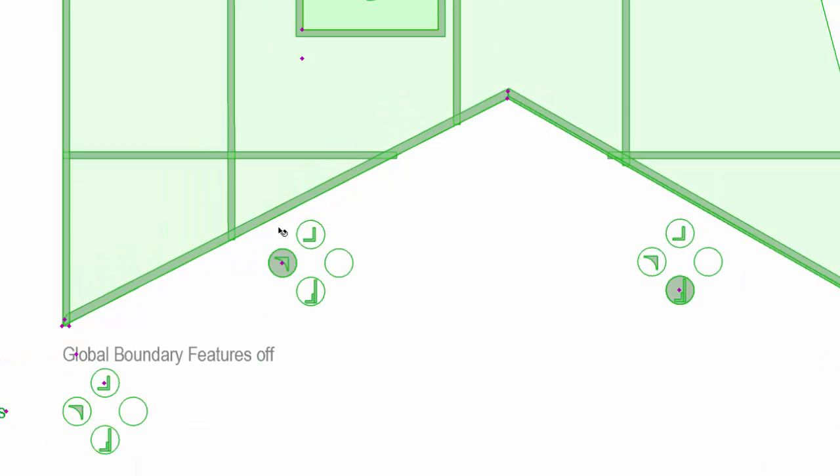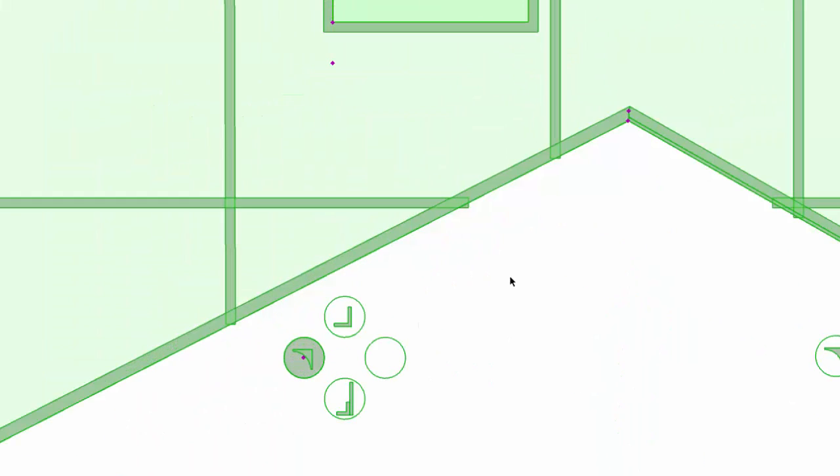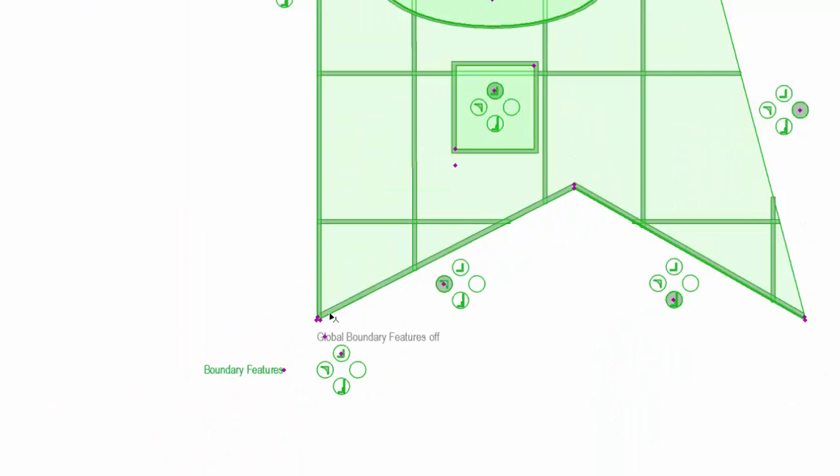So let's have a look at that. Down here we have a joint and we have a cornice. Now I'm assuming they're slightly different widths. In fact, yes, they are. So if we nominate the bisector, ArchiCAD kindly gives us that. So if we just pan around a bit, we get to the bisector eventually.